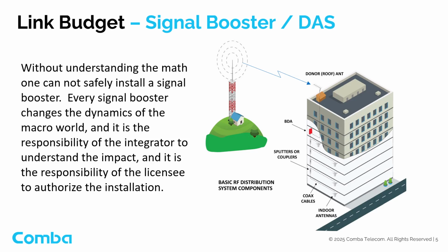Without understanding the math involved in an RF link budget, one cannot safely install a signal booster or BDA. Every signal booster changes the dynamics of the macro world. It is the responsibility of the AHJ and licensee to authorize the design, installation, and turn-up of the system. It is the integrator's responsibility to evaluate how the BDA will affect the surrounding macro environment and to determine the